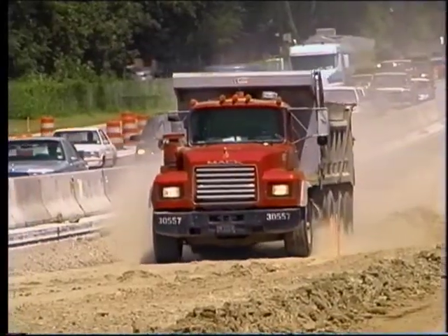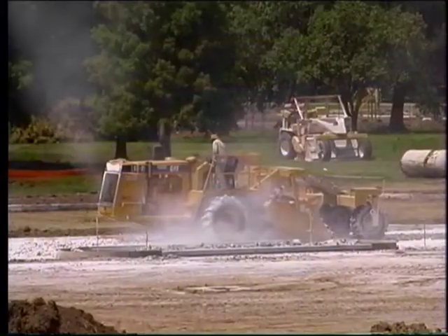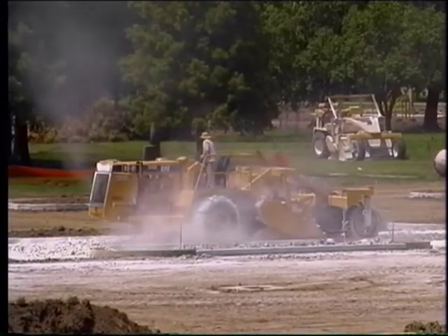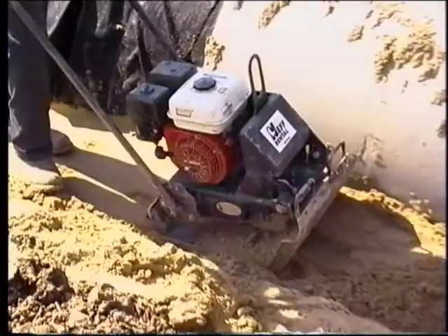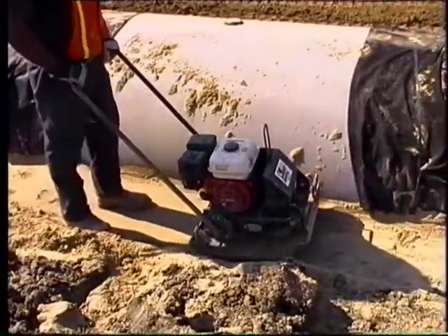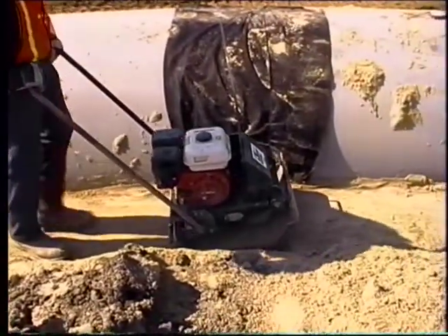Some soil, in its raw state, will not be suitable to use for construction purposes. To make a soil mass stronger and better able to support traffic loads, we compact the soil during the construction process to make it more dense. Then we perform tests to measure the in-place density of the soil to determine if it meets the minimum density required by the department's specifications.